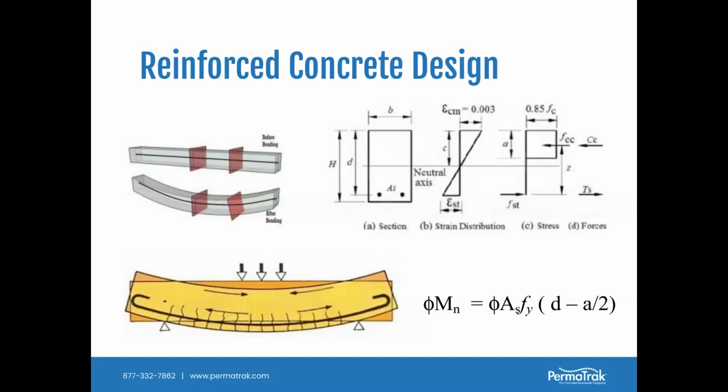So the concrete capacity of the beam is then computed by the formula you see on the right-hand side. It's a function of a couple of things: the amount of steel you put in the beam in the tension zone, plus the geometry of the beam itself, so the width and the height of the beam. A concrete member has the flexibility of allowing itself to adjust to the loading. So the width and the height and the amount of steel can all be variable, right? These are typically made to fit whatever the design loads are.